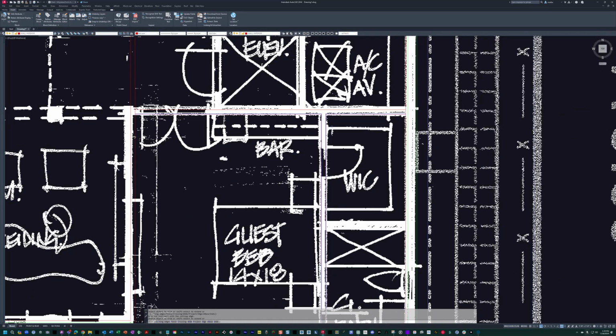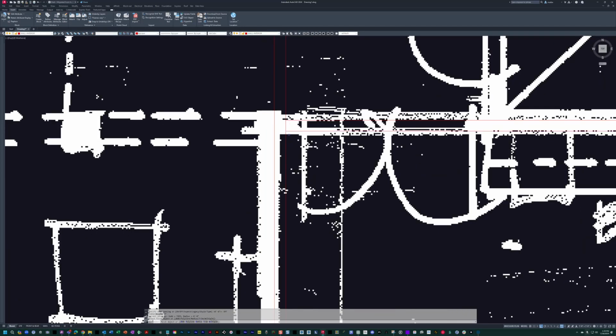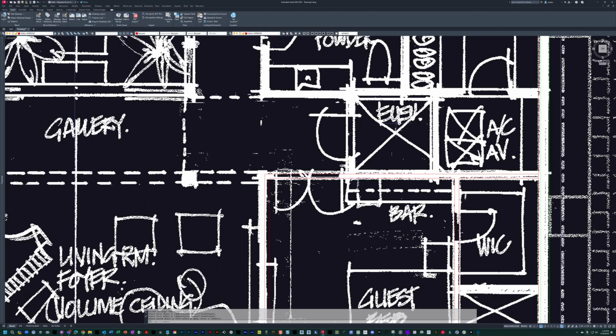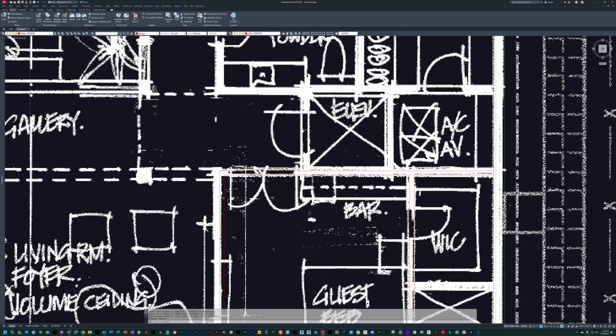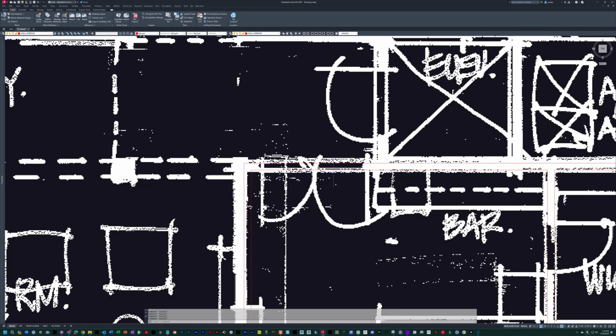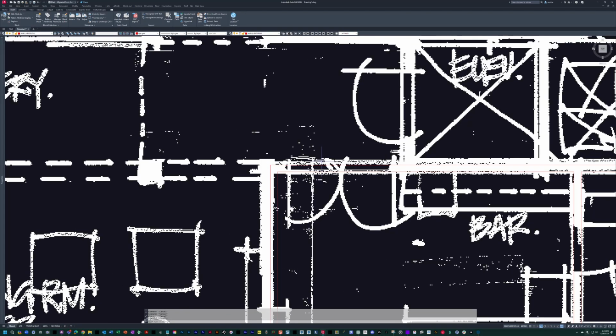So just going to continue on and block all this out. I know that this is going to cut and cut. All right. Now looking at this door and this elevator, we're going to go through this real quick, then we're going to jump back into the bathroom. I see it's a double door. I generally like to not use anything less than a double 2.6, especially when we're dealing with 8 to 10 foot interior doors. 2 foot 4 or even 2 foot doors, they just look so skinny, even though it ends up being a 4 foot opening at 2 foot doors. It's just so skinny looking, it looks out of scale.